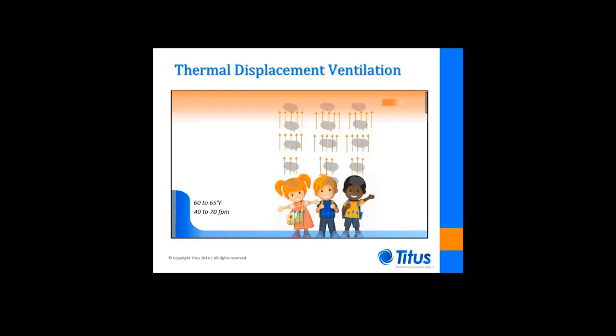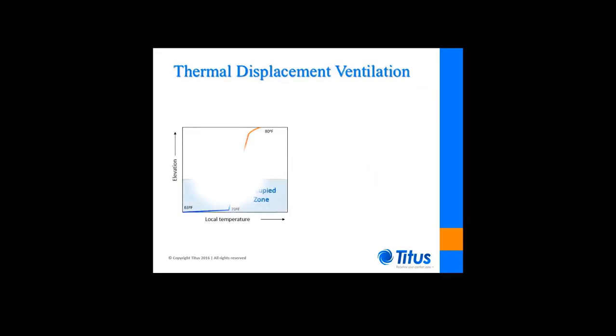Heat gains such as those from lights that originate above the conditioned air reservoir escape naturally and do not affect the amount of air required to condition the occupants of the space. This figure relates to temperature relationships for a thermal displacement system. Note the temperature gradients between the ankle and the return air levels. This gradient forms as a result of space heat gains that occur above the supply air layer.